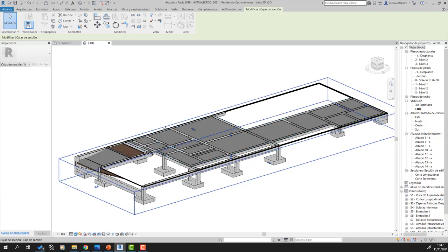One of the functions of these foundation beams is to give a kind of stiffness to the system, and by stiffness I mean the amount of movement that a certain body has when forces are applied on it. You don't need to master the concept right now because we are studying this at a schematic level. And as you can see, the foundation beams connect this portion of the footings with the surrounding or neighboring footings.